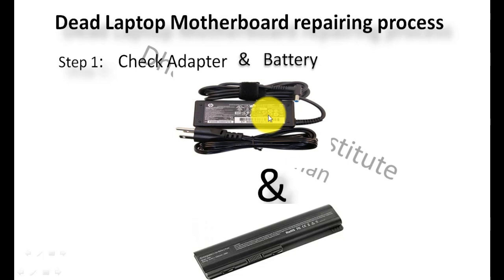Secondly, check your battery by unplugging it from the laptop and insert a good adapter and see whether the laptop opens or not, because the battery sometimes can also be the reason for the laptop's dead problem. If you find the adapter and battery okay, then you can be sure that it is the laptop's motherboard fault.